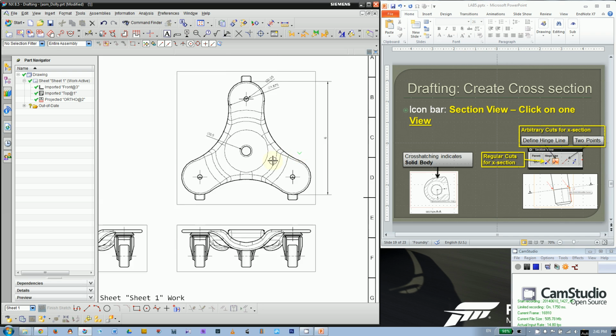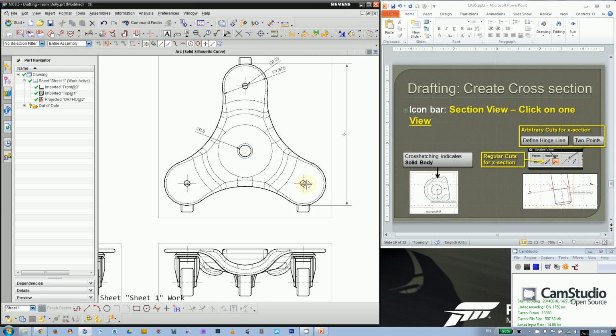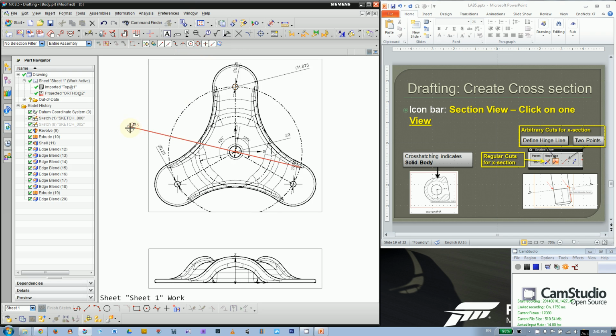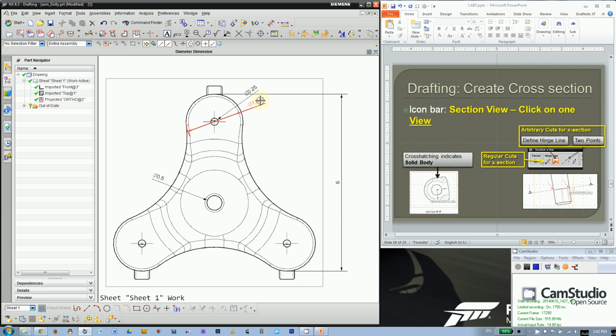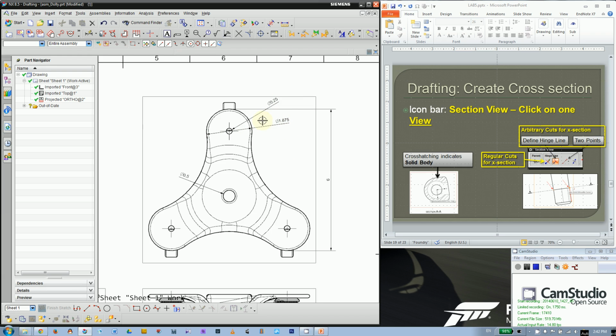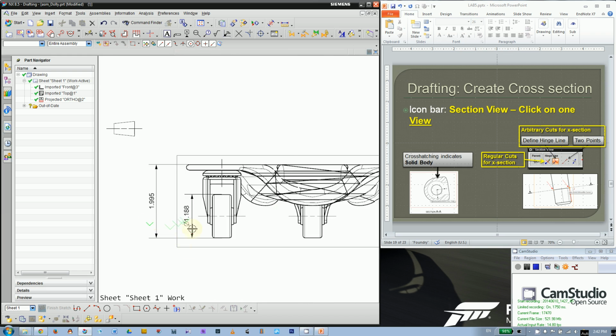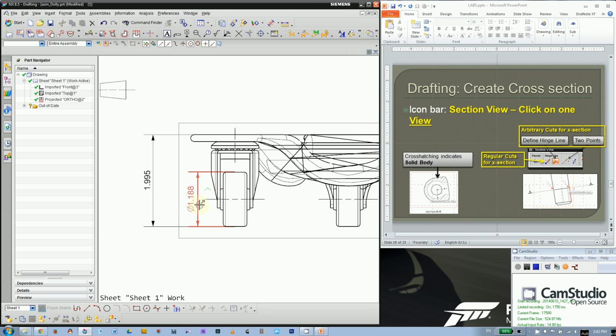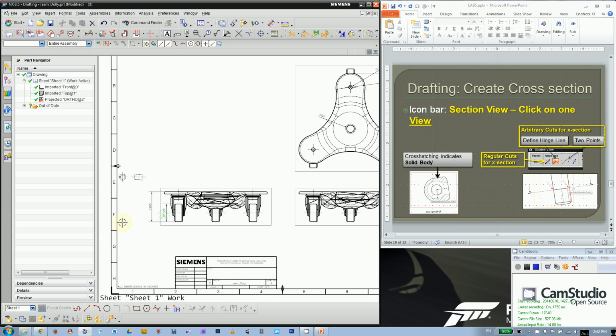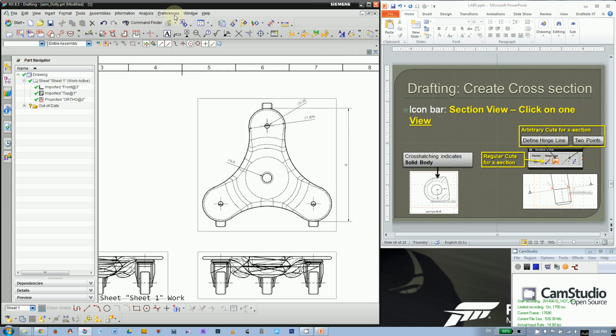Alright, now let's go back to this assembly. Okay, and as I said, the position of the holes is actually on a circle. So if you look at this, you can add this radius here. Okay, now next step, we need to format the dimensions. For example, some of the dimensions are in fraction. Okay, and you don't want to see, for example, this dimension, it's actually rounded up from a more accurate number. So how do we change the format of a dimension?